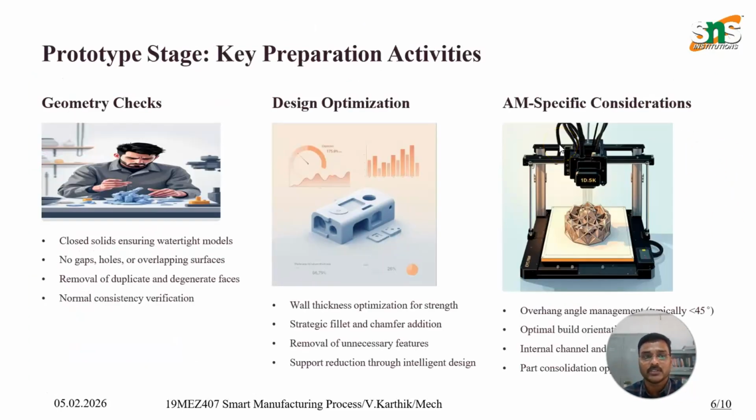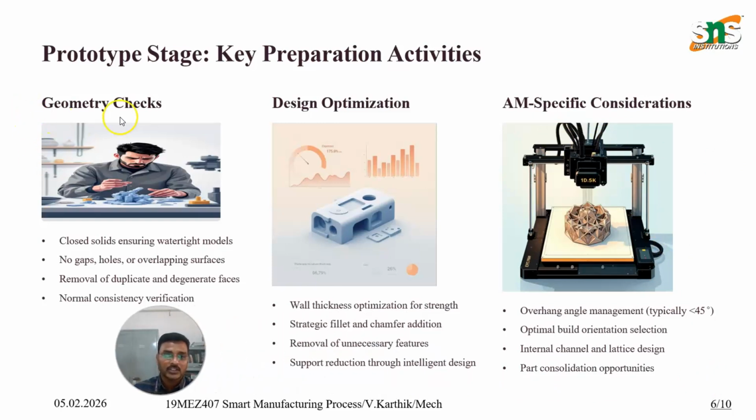Then the prototype stage, where before going for the actual product, we can make simulations or prototype checks. These are the activities: geometry checks, design optimization, and additive manufacturing specific considerations. For geometry checks, we can check closed solids ensuring watertight models, no gaps, holes or overlapping surfaces, removal of duplicate and degenerate faces, and normal consistency and verification. Design